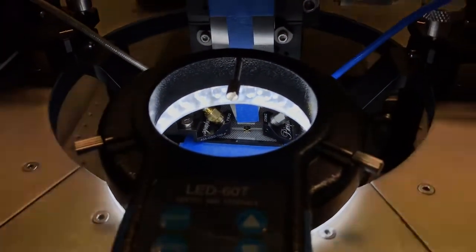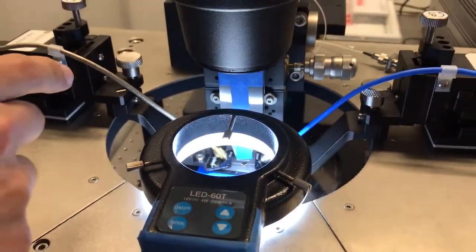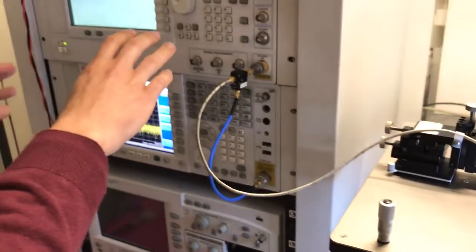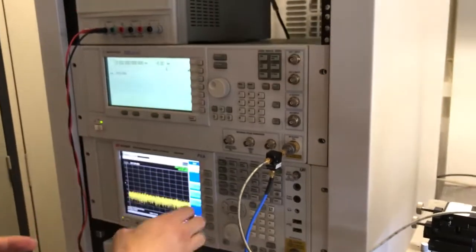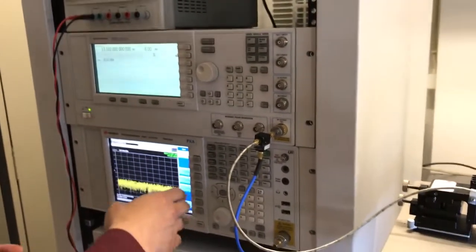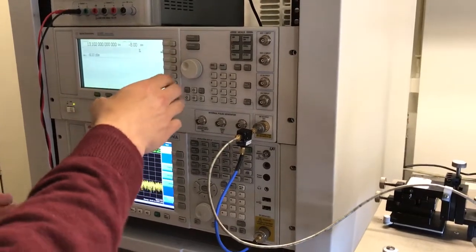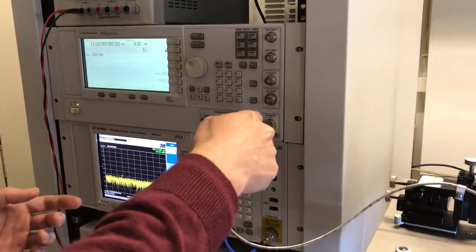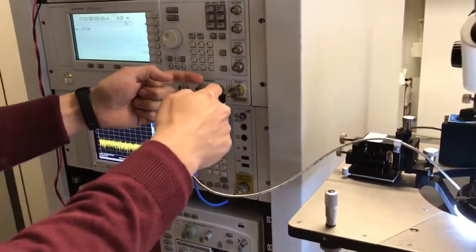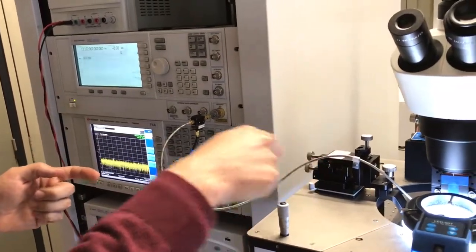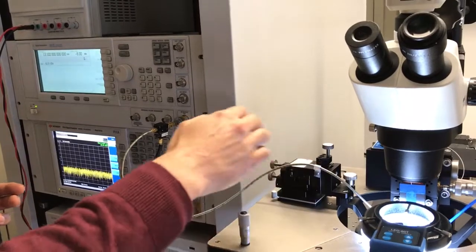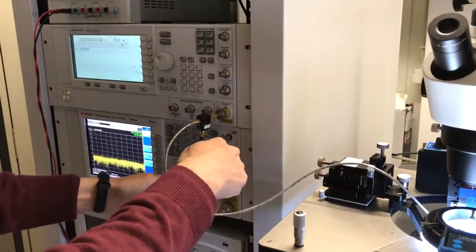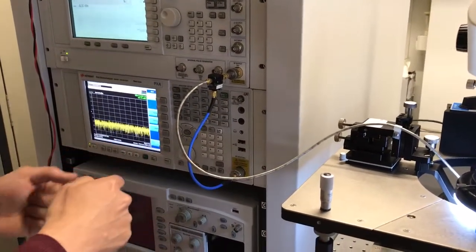So this 13 gigahertz signal then comes out of the RTD through this RF cable, and it's connected to a set of equipments that are here. So we have a signal generator and the signal analyzer or spectrum analyzer. So the signal generator is used to injection lock the RTD-PD at its output. So we use an electrical circulator. So the signal comes from the signal generator, goes through the circulator, goes into the RTD, and then the RTD signal that comes from in this direction will pass the circulator into the signal analyzer.